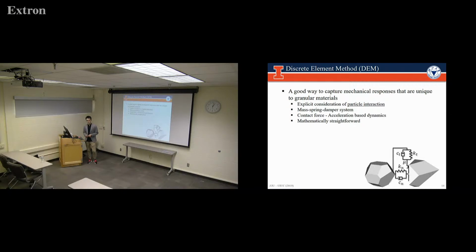Not with temperature, maybe like water. If there is no good drainage, maybe it might accumulate. We don't model water inside the DEM models because water is kind of a continuous thing. So usually we don't model the water in DEM, but we do have fouled ballast particles, and to model those fouled ballast layers, we can change the parameters we input into the DEM model.